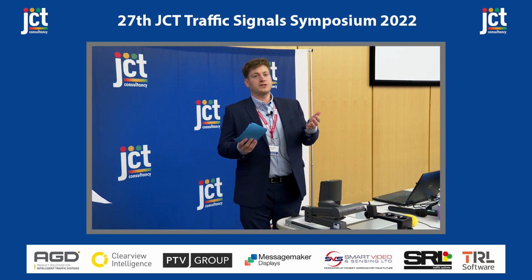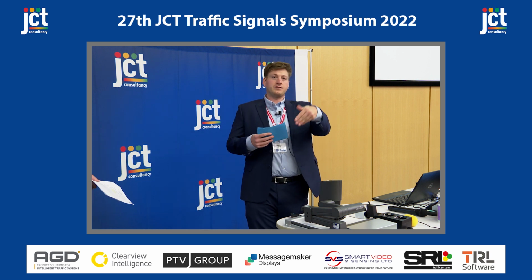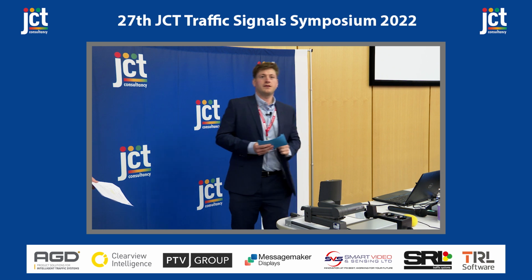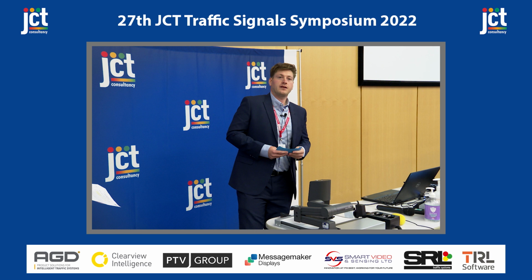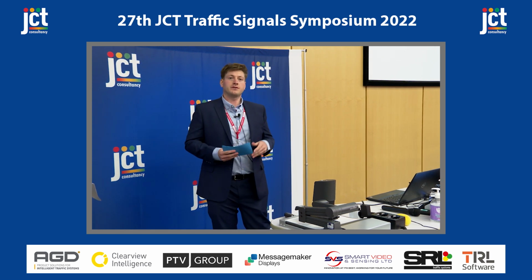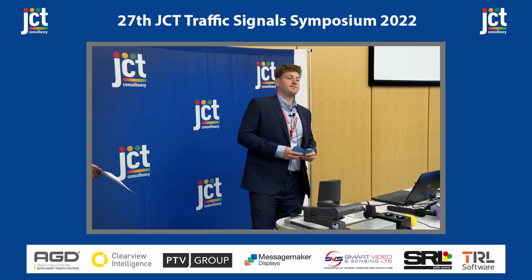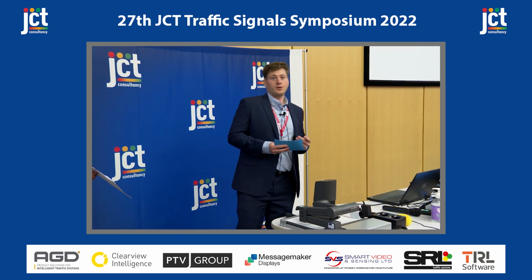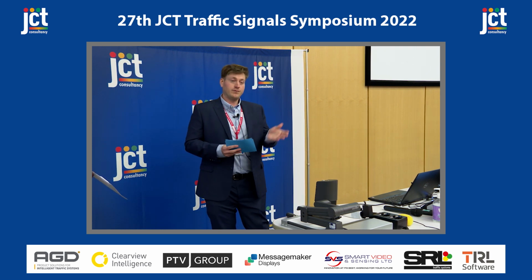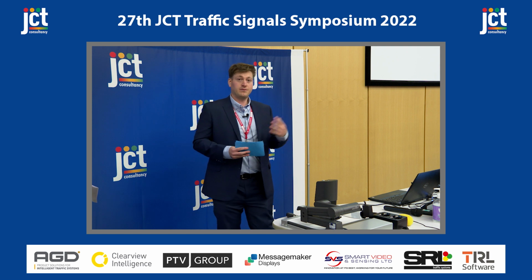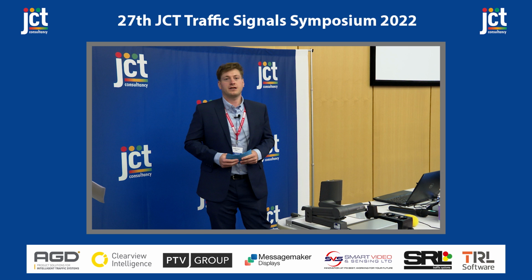For cyclists that want to feel safe, stay within the cycle track lane and then use the appropriate crossing across the road. You'd think, hopefully, once the cycling numbers increase, a cyclist wouldn't breach the pedestrian crossings. But if you feel it's a real hazard, that there's a desire line for cyclists to turn right there and not actually use the cycle track in the two phases in one stage, then you can put additional signage up.